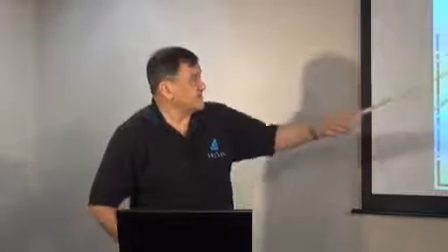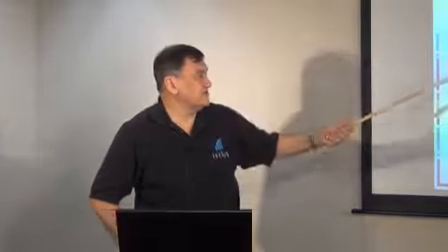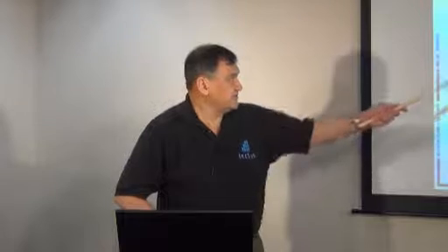And that is that set of system operating limits that will lead to instability, uncontrolled separation, or cascading outages, which will, of course, affect the reliability of the bulk electric system and can leave millions or tens of millions of customers in the dark. That's the goal. Normally those limits will be identified for you ahead of time by your engineering staff. But if for some reason the system gets into a very unusual condition, you may have to actually figure out for yourself which of those interconnection operating limits and take some action to alert